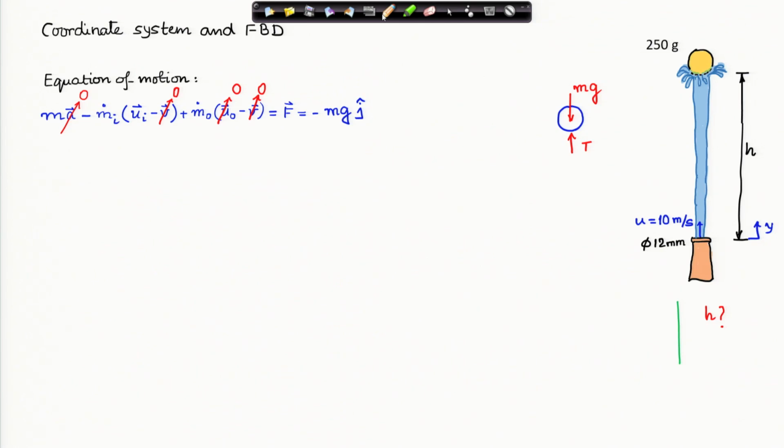In the third term, there is no outflow velocity. What we are assuming is that water particles are coming, hitting the ball, and because they are hitting the ball, they stop there. The water particles come to rest. Therefore, the absolute outgoing velocity of the water particles, u0, is 0, and the velocity of the ball is already 0.